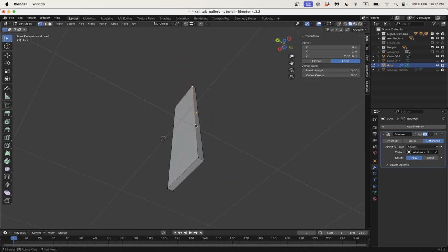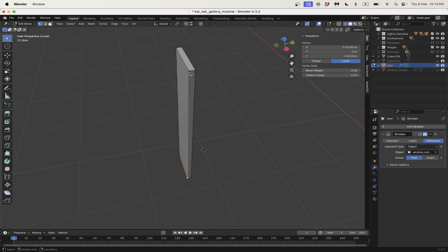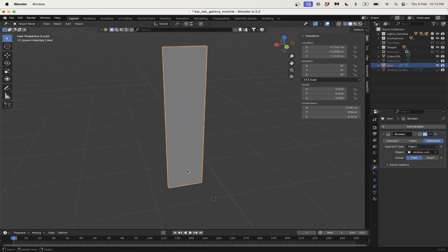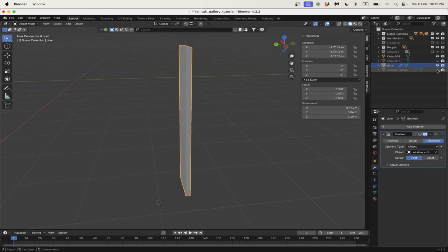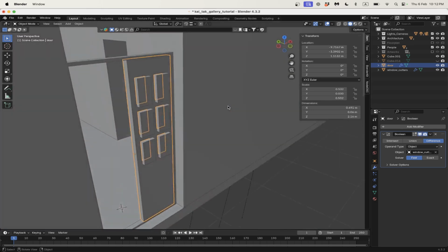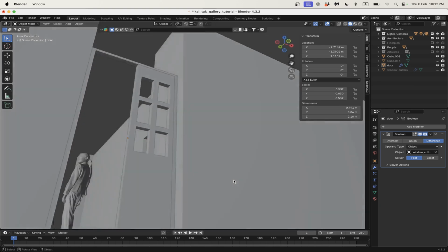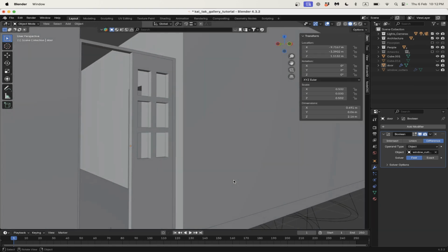Looks okay to me. There's no holes in it. A Boolean operation often will fail if your object has holes in it or overlapping vertexes or anything like that. But this all looks perfectly fine. So until I can work out what I've done, let's just leave that there. I'll put it on fast, turn my Boolean cutter back on, or make it visible with the viewport visibility. And if I hide these cutters, we can see that now we've got our windows.